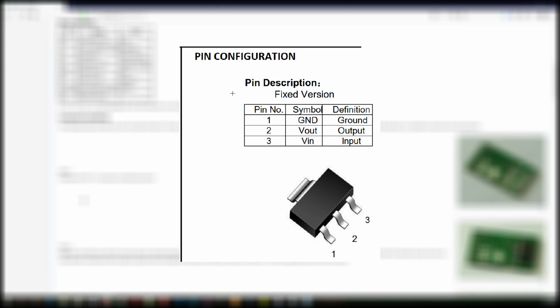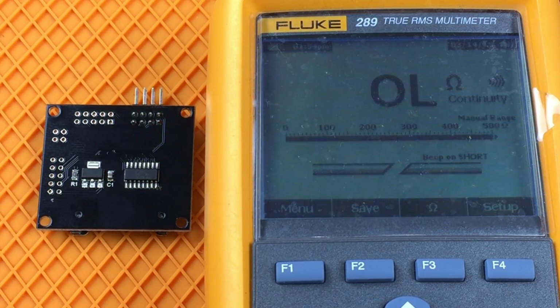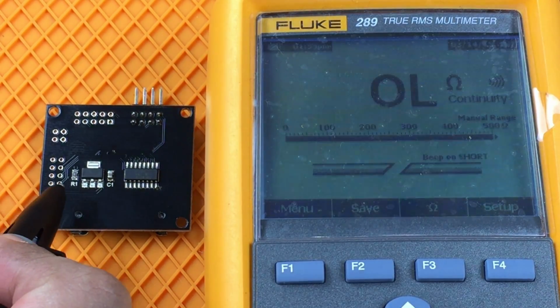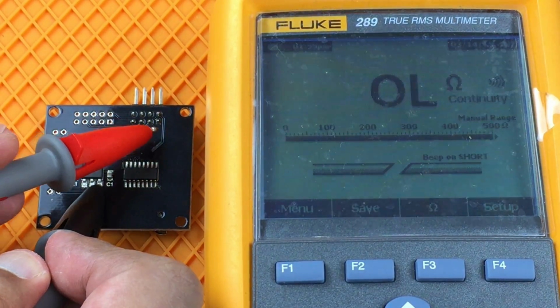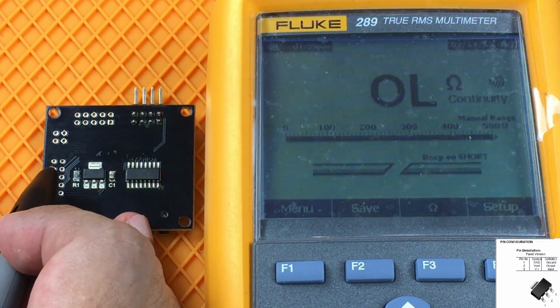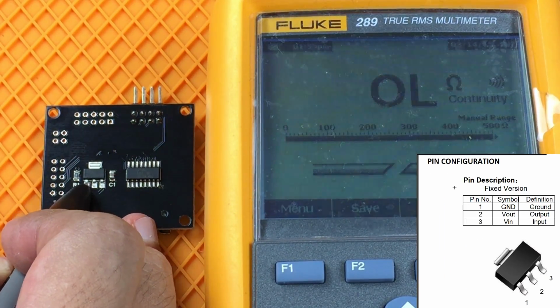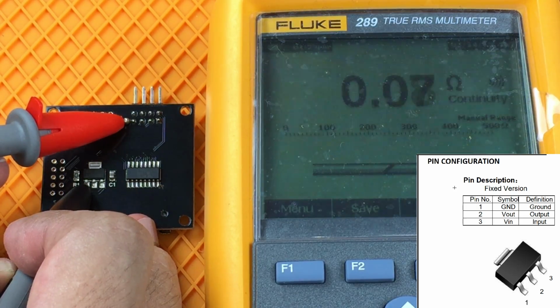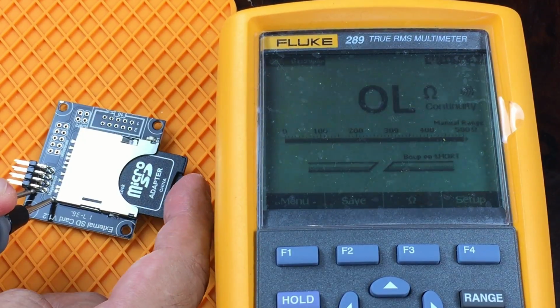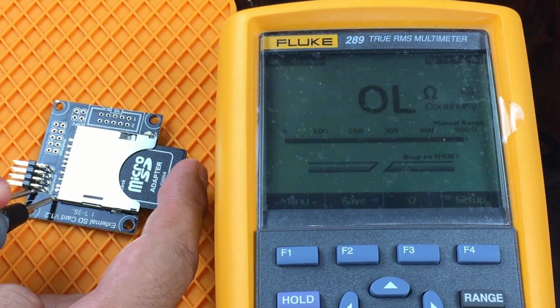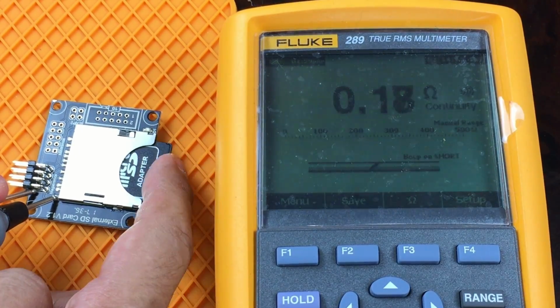Observe the pin Vin from the pinout of the AMS1117 IC's datasheet. Using a multimeter, we can trace the supply pin's connection to the header and compare the position with the one on the SD-RAMPS. We see that the input voltage is connected to the square pad, which is pin 1, or labeled as 5 volt on the SD-RAMPS. Similarly, the ground pin is connected to pin 7 on the header, also known as GND on the SD-RAMPS. After some probing, the SD detect pin was found to be connected to pin 2 on the header, which is identified as D49 on the SD-RAMPS.